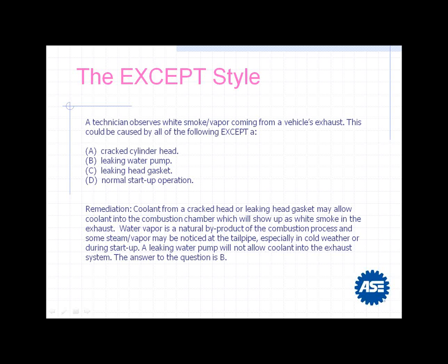So some steam and vapor may be noticed out of the tailpipe, especially in cold weather and during startup. Good point of distinction. It'll usually burn off. Any accumulated water vapor in the exhaust system will burn off after the exhaust system heats up and evaporates it. But that's what we say. It could be normal startup operation. However, a leaking water pump shouldn't allow coolant in the exhaust system. So that's the answer we're looking for. We're looking for the one that won't cause it. In this case, the leaking water pump, and the option there is B. Okay.